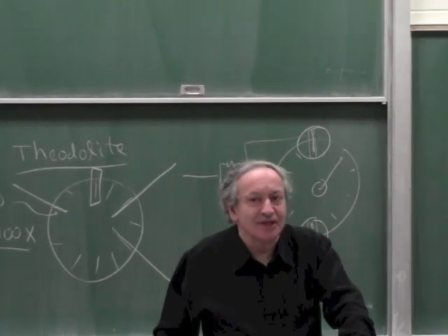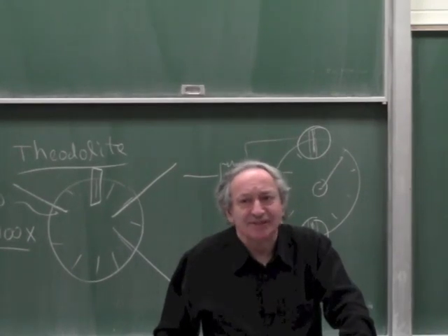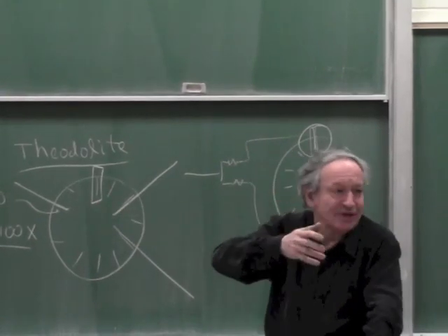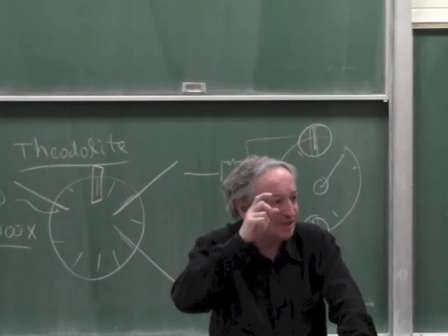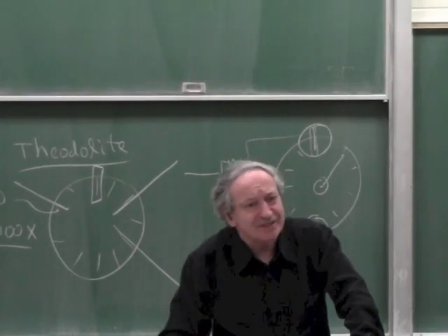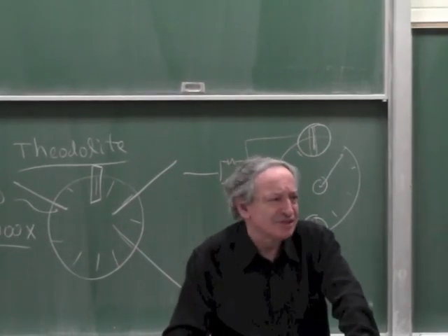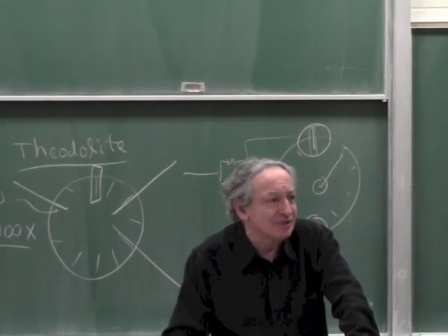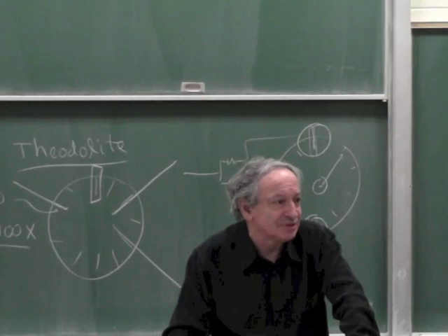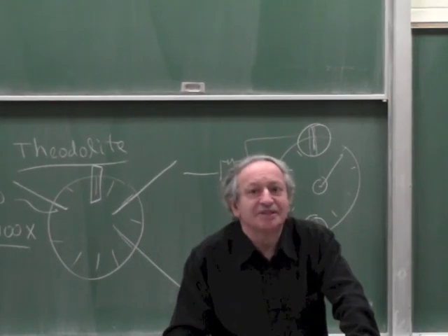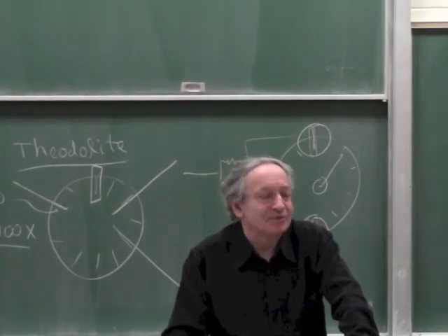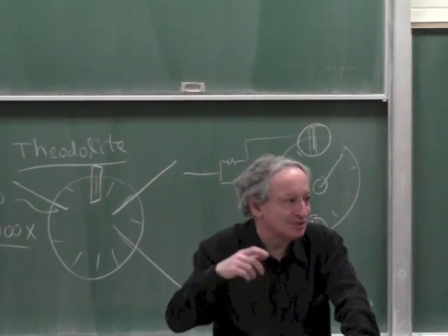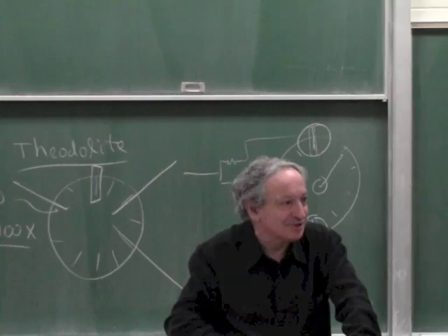Correct, although the lens of the camera has a slight distortion. The camera itself doesn't, because it's made on a lithographic machine. It's deadly accurate, but the lens. But the distortion of lenses is very small. Like, it's easy to get a lens which is 0.1% or even 0.01% distortion. And it's always the same, so you can take it out with a lookup table. You can look at a grid, calibrate the distortion with a lookup table, and you always multiply by this lookup table.